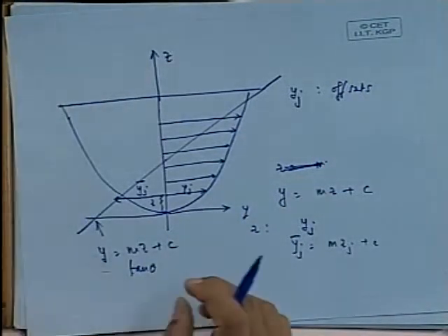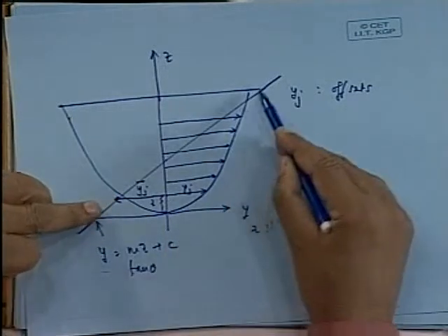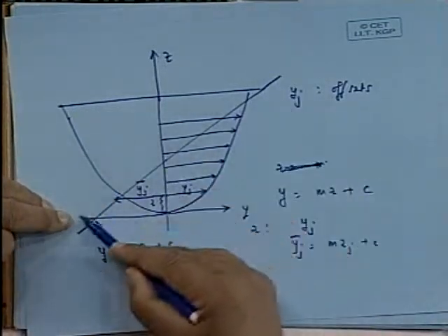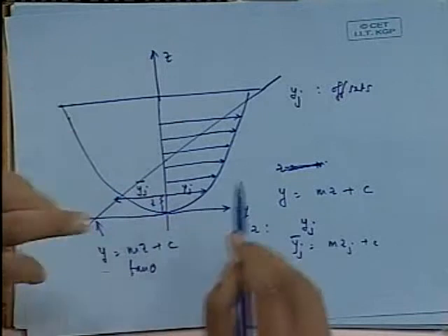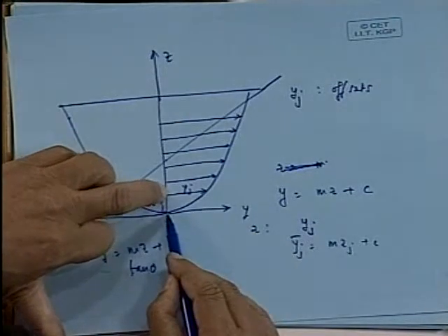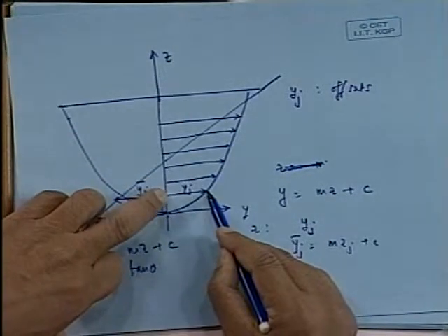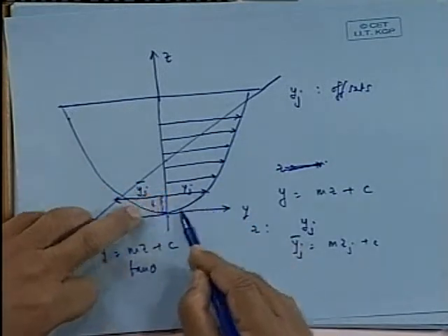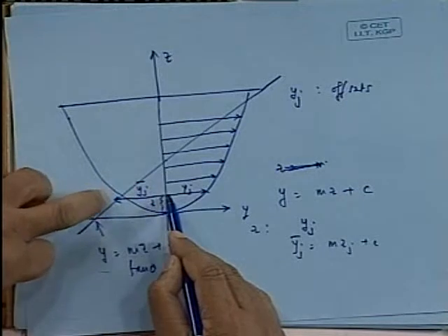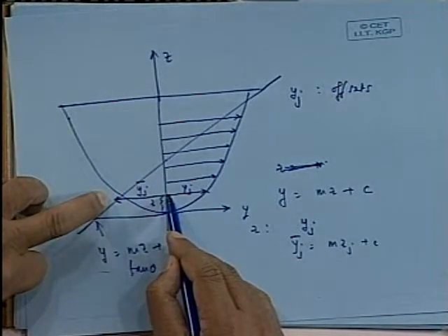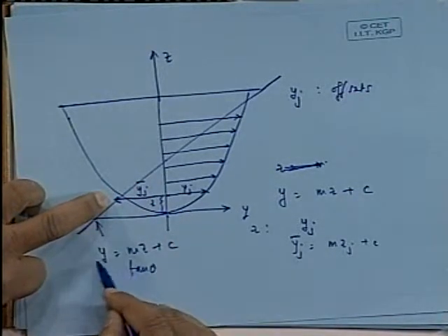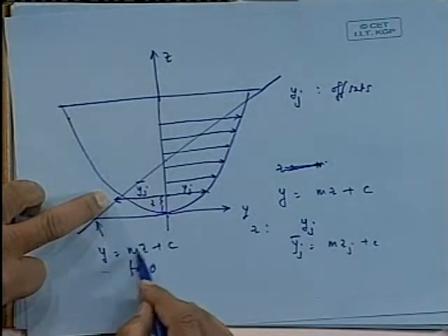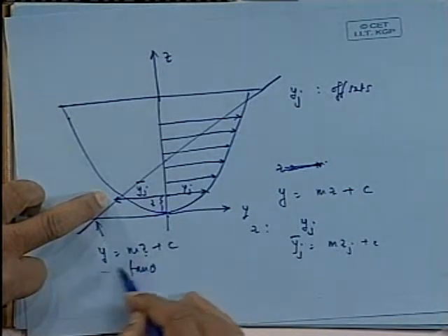Now let us see carefully. I have this line equation known. Now I take a given water line. So at this water line, I know this. This is my offset table. Say 1 meter, I have z equal to 1 meter. I find out what is the intercept here from this equation. I just put the z value to be 1 meter in this, and I will get this y. So I have got this.